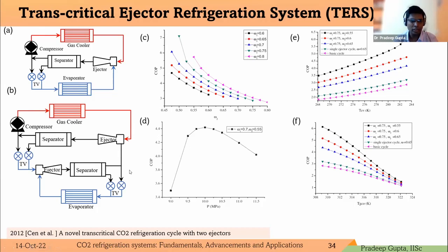Okay. As of now, I had that. And again, you see in this, two throttle valves are given. Yes, sir, those throttle valves are for control issues. One is for liquid, one is for vapor. Sometimes the ejector entrainment ratio clashes with the dryness fraction at the end of the separator. To resolve that issue, we have provided these two throttle valves here.